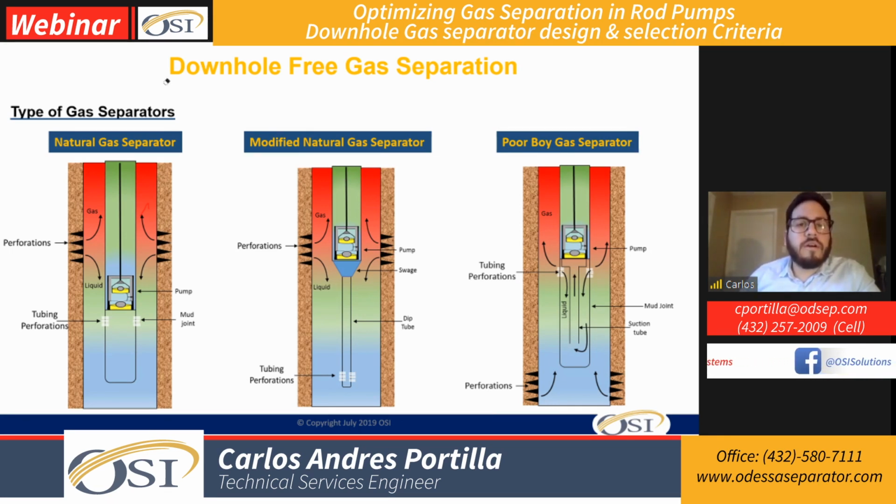Now we have our modified natural gas separator. In this case, we're installing the pump right in front of the perforations. So what we do is install an extension, in this case the dip tube, all right, with the intake at the very bottom to simulate the same concept as the natural gas separator. Basically, it's the same concept. The gas bubbles, due to density, will always try to flow up. So that's the principle of the modified natural gas separator.